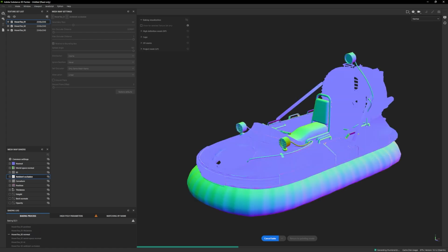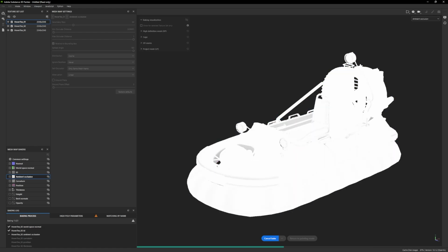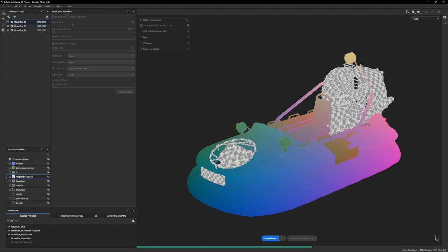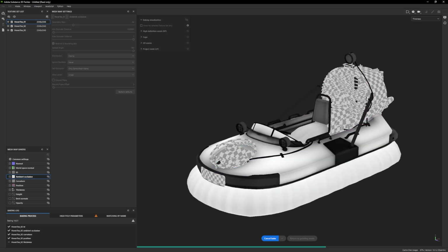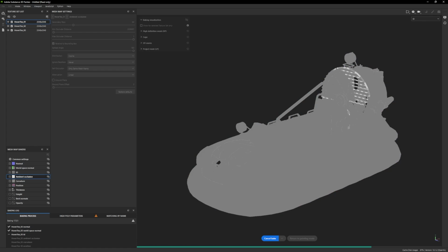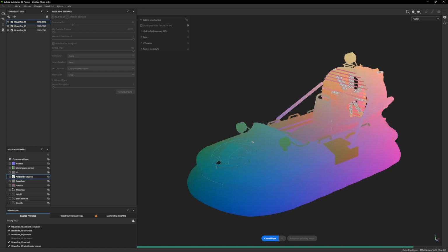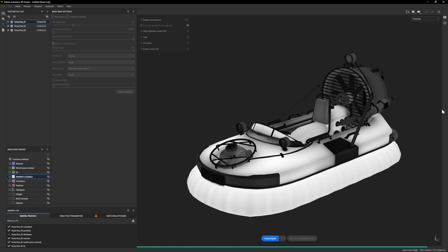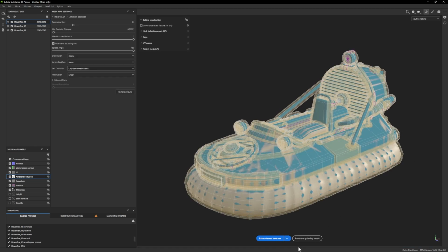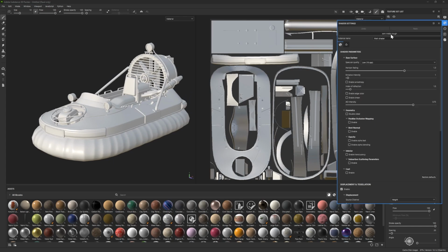So when I'm working in Substance Painter and I want to get my texturing out really quickly, I'm going to try to take advantage of those smart materials. They are great to use as some sort of base or foundation that you can start working off of. So that's basically what we're going to do. We are going to start throwing on random materials onto these meshes. And then we can start refining them afterwards, start tweaking things, adding fill layers with different grunge values and different dirt values. That way we can have some dirt and grime on top of these materials.